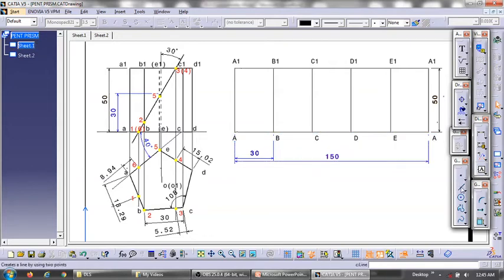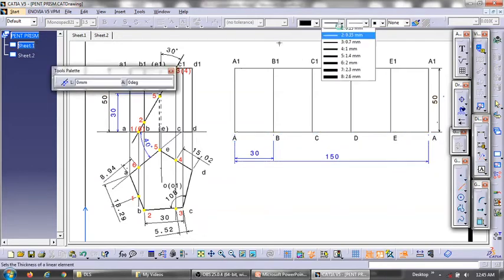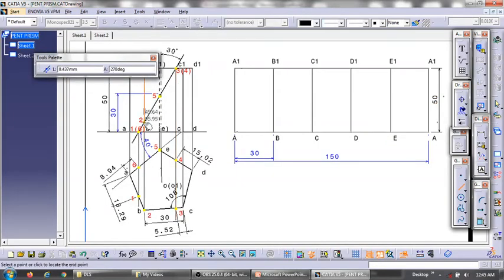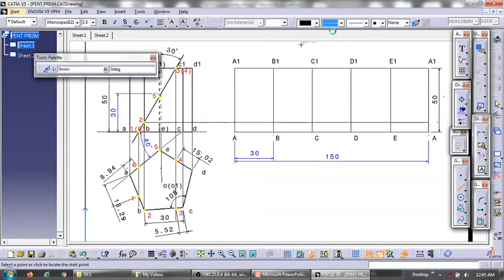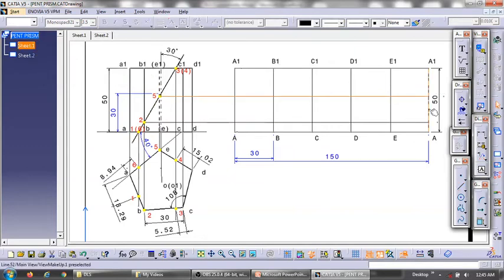So we'll draw the projection lines, thin lines, from 2 and from 5, only these two, because only at 2 and 5 we are getting the true length in the front view. So I just need two projections, one for 2 and one for 5. So I'll locate these two intersection points first.